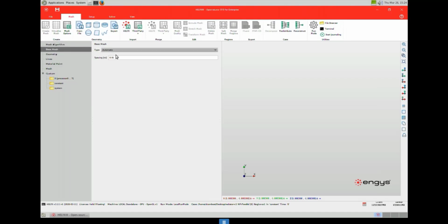Base mesh: since we're using a cut cell approach, you have to generate a background mesh, and then from that background mesh, you cut out your STL geometries. It'll refine where the geometry intersects the background mesh, then we'll add layers, sweep away cells that we don't need, and snap these cells to the surface of the STL and regain our original geometry. I'll show you exactly what that means. All right, so let me start by choosing a background mesh and using the default. Let me import my geometry.